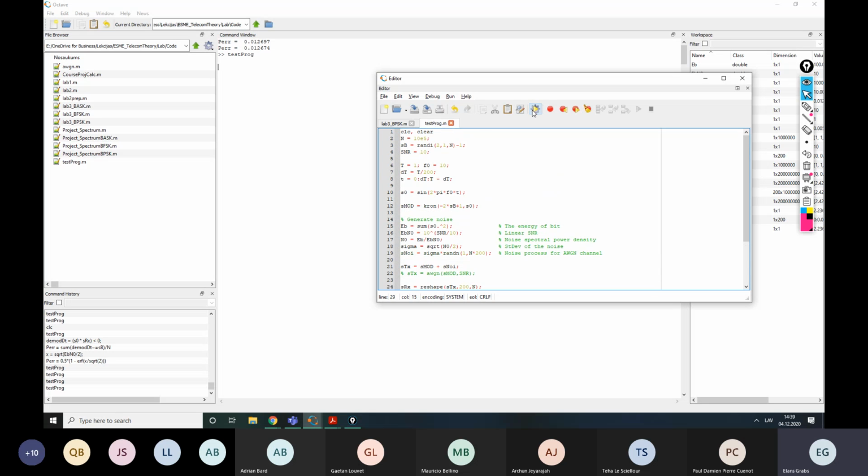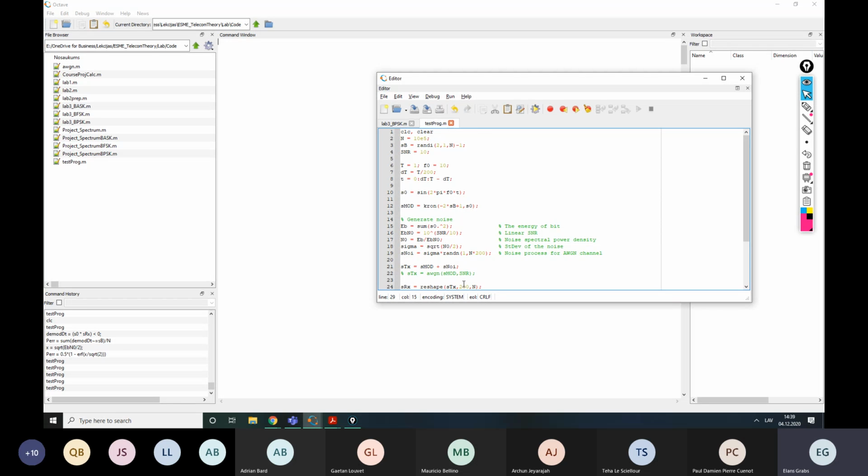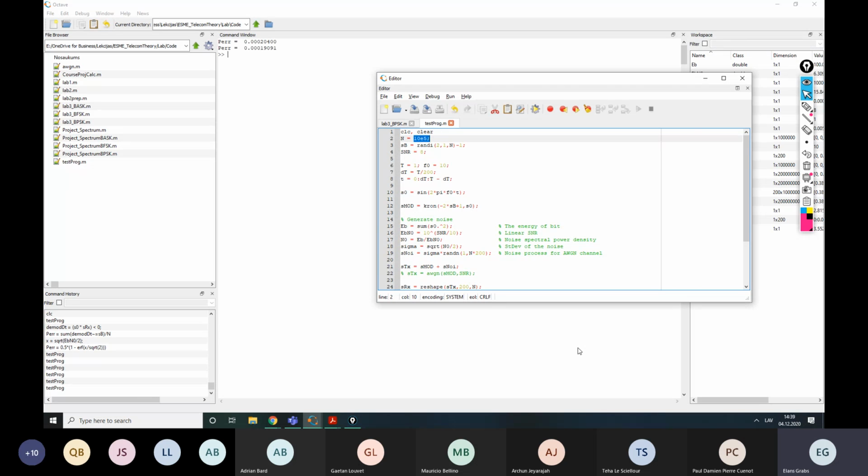And for phase shift keying, I have changed both the formula, since it's a little bit different, and the simulation parameters. And because the signal to noise ratio is not so small, we need to change it to, for example, maybe 8, so that this value is much better. Because we would need to put infinity here and wait for entire infinity to actually obtain this theoretical result, which sadly we don't have time for. Let's assume that these results do match.